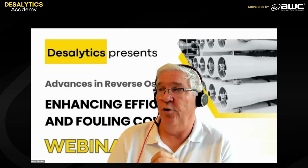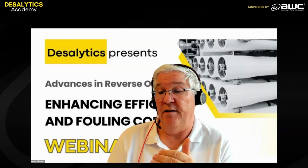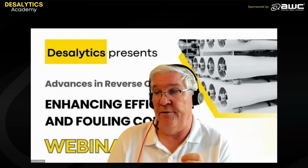Another project in Morocco, 5,000 cubic meter per day, recently installed, where we also run in front of a seawater RO plant. We are using 14 vertical filters at around 12 meters per hour filtration velocity. Important to mention is we can actually run our media up to 20, even 25 meters per hour filtration velocity, which will give you a huge savings on surface area and capex for your filters.